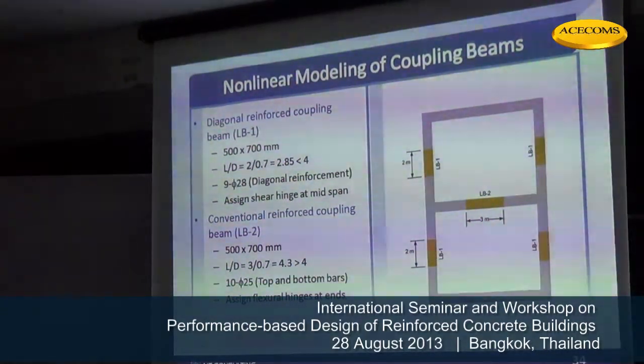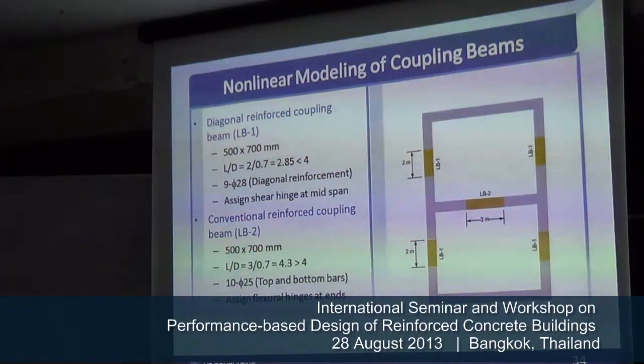This is the shear wall reinforcement layout. In this building, I use this green zone. I use vertical reinforcement of 0.8% and confinement reinforcement of 15 legs, 12 millimeter diameter bars at 150 millimeter spacing. It means